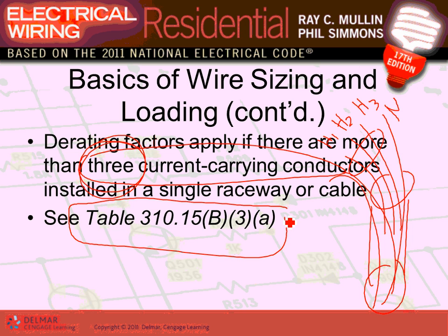For example, if your conductor is number 12, back to number 12, can give me 30 amps. Now, if I grab 4 current-carrying conductors, the code says you have to cut this number by 0.8, and we'll get to this one. What's 0.8 of 30? So 8 times 3, 24, right?